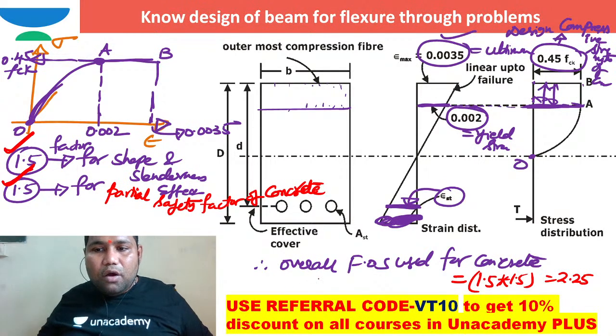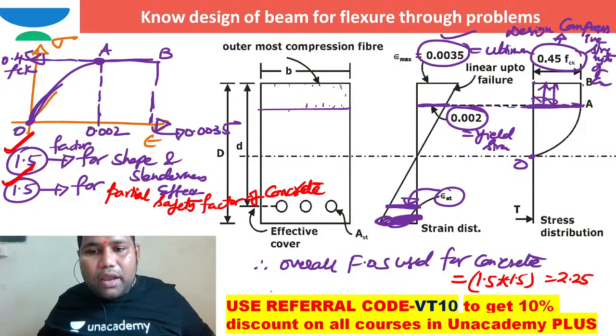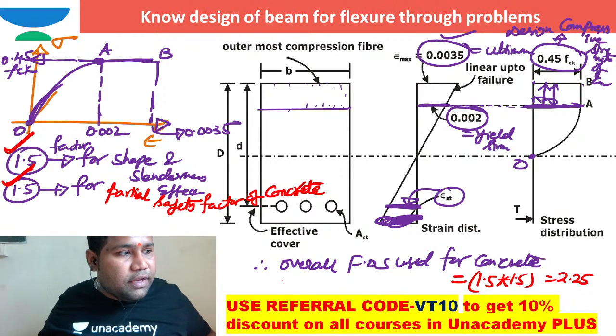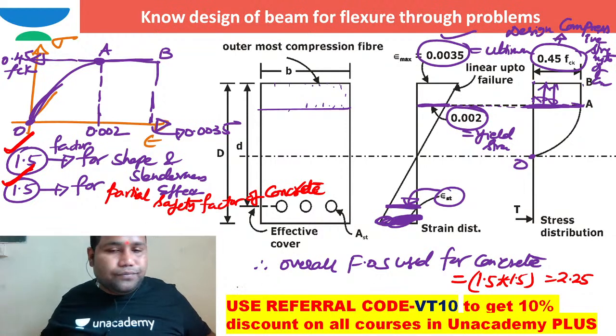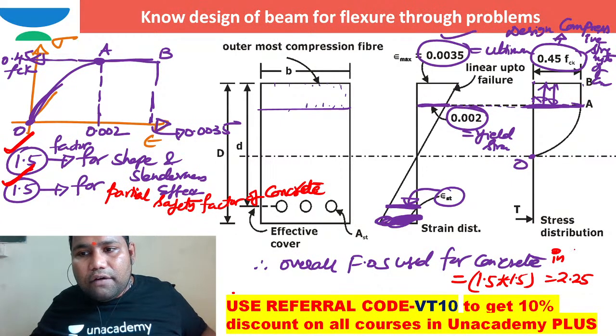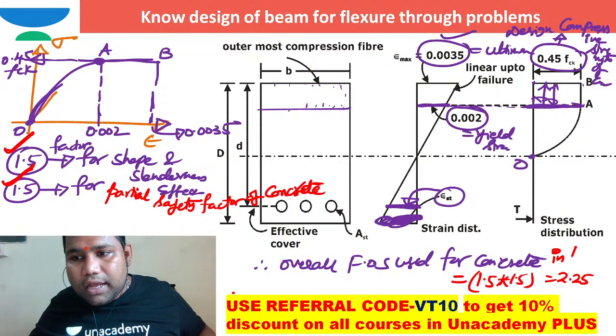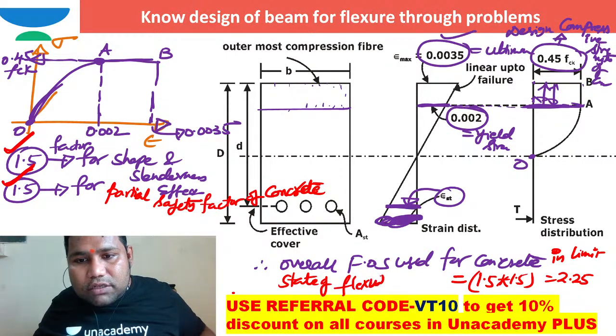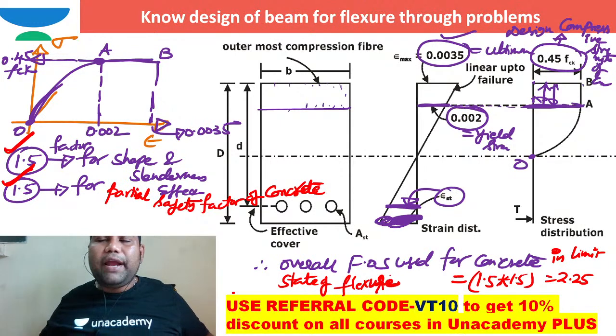If you write 1 divided by 2.25, you will end up with 0.446 fck, which is 0.45 fck. So I can say the overall factor of safety used for concrete in limit state of flexure is not just 1.5, it is 2.25.